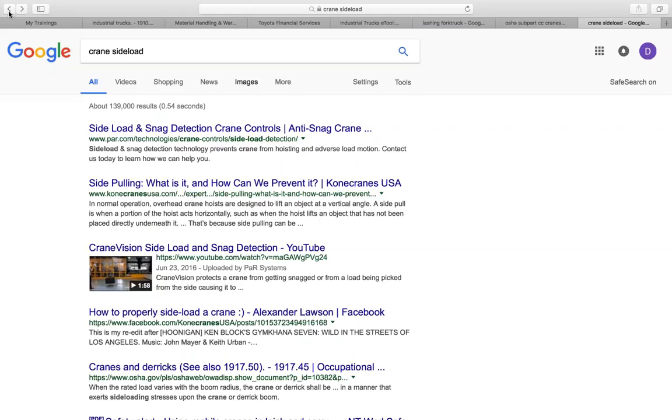It's going to be 45,000 pounds, and 75% of that is going to put us around 33,750, something like that, or about 32.5 would be the critical lift moment.